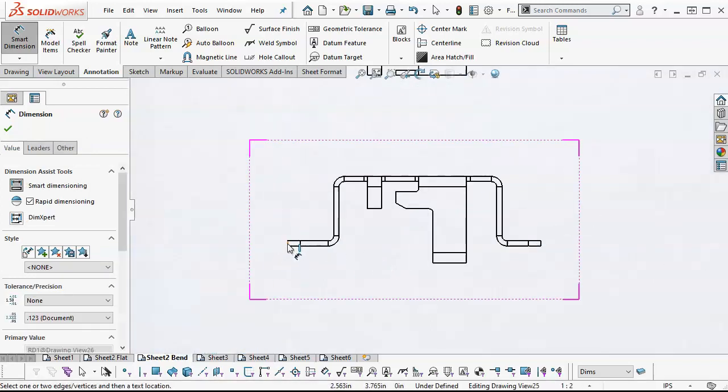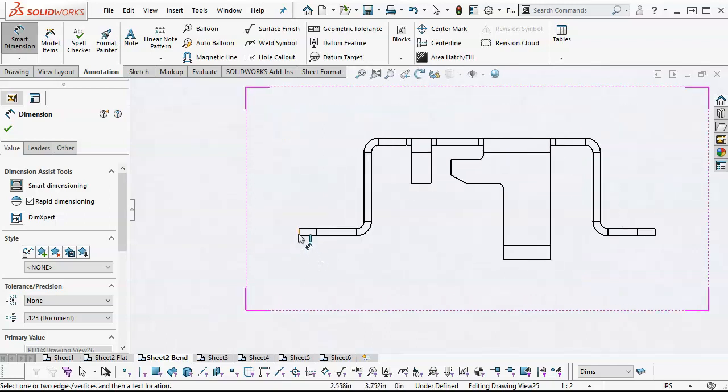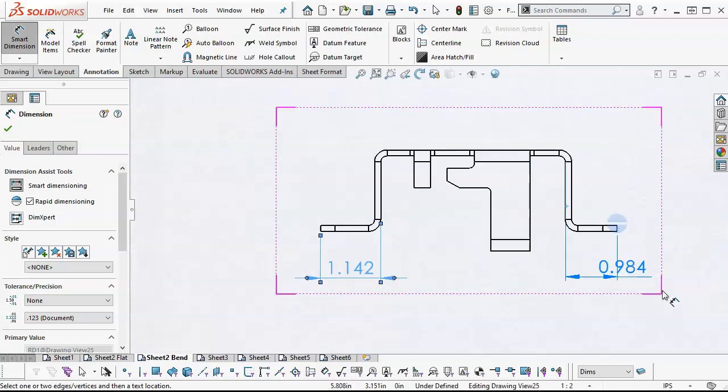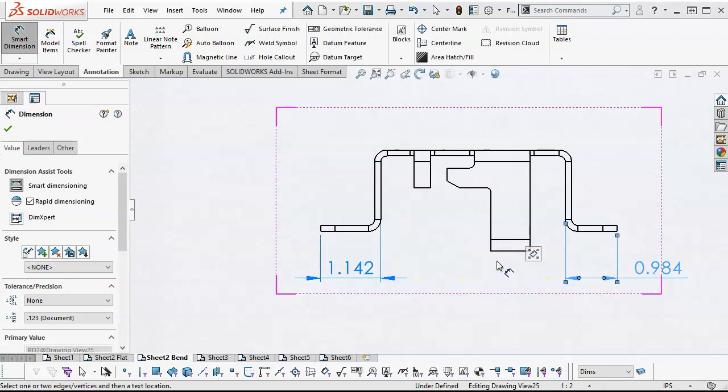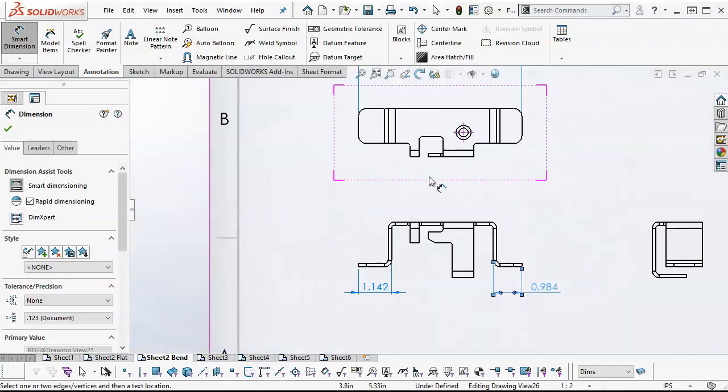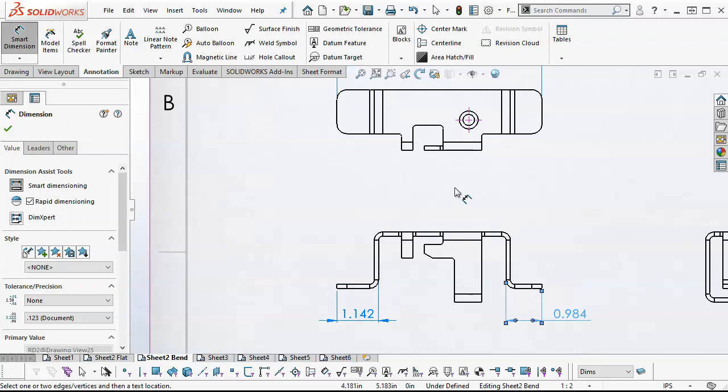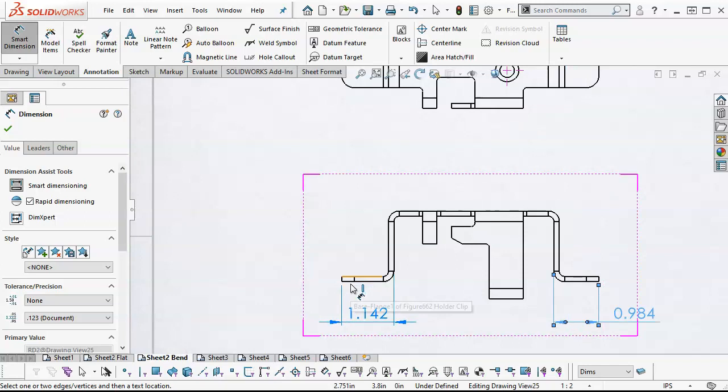So if I'm going to give locations, I would like to have locations that I can measure from. So if I knew in a lot better terms what this was doing, what it had to fit, and what the critical dimensions were, then I could make some better decisions. So a lot of these dimensions are driven by the flat pattern, so I wouldn't necessarily have to come back to all of these intermediate positions.